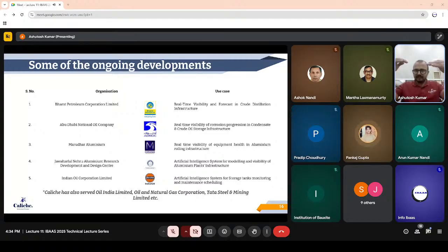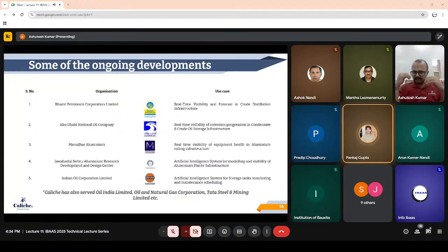And sir, actually in our application, we are storing all this data at 5 milliseconds. Because the mill, I'm talking about the cold rolling mill, the speed there is so high. So if you do not generate this data at every 5 milliseconds, for any abnormality, any catastrophic condition, we cannot analyze it later. So we have to generate this data at every 5 milliseconds.